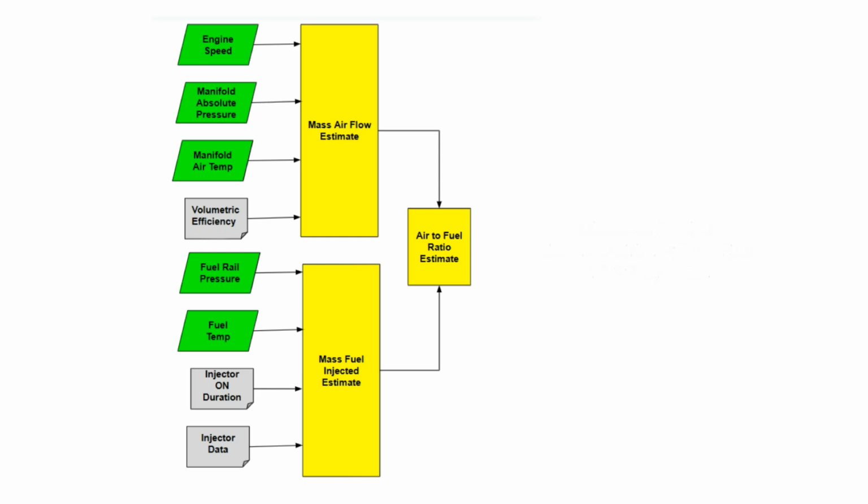However, you would seldom see a modern diesel engine being operated at this rich of an air-fuel ratio. Instead, the air-fuel ratio under load for a diesel engine may be 20 to 1 or even more. Diesel engine air-fuel ratio at low loads may be 40 to 1 or higher. Obviously, if this were a spark ignition gasoline engine, it would lean misfire at these high air-to-fuel ratios.